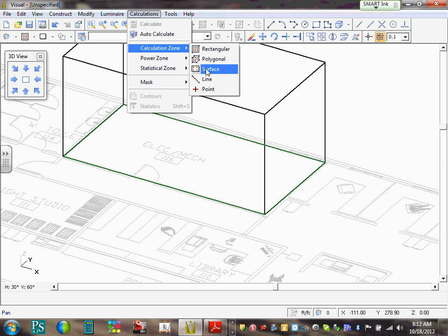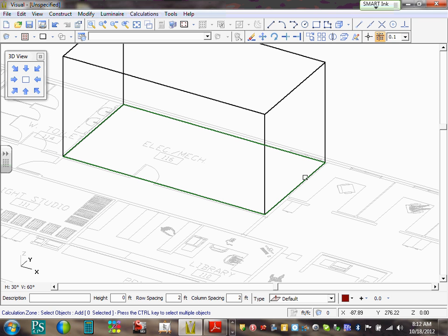Thumbs up, Chad? Okay. Now, I want to click surface, always. Click surface, and before you click anywhere else, do you see the selection box that you have? I want to select the floor, because if you select the walls, the calculation will be on the walls. So click on the floor, that green stuff here. Don't click anywhere else. Do you guys have the red here? If the red came on this wall, you picked the wrong wall. It has to be the floor, right?